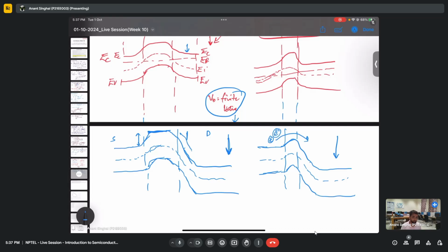This is happening because of a certain phenomenon. So what is happening? We are having a drain induced barrier lowering, that is, by inducing the drain voltage, we are having a barrier lowering. This is what we call DIBL. And this only happens in short channel devices because of this particular barrier. It has a certain impact when we have long channel devices, where we have a certain barrier.